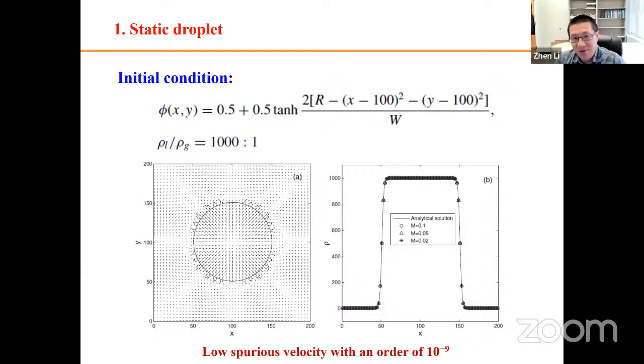Yeah, but if you do not use a non-uniform mesh, then the computational cost will be extremely high because the interface is very sharp, right? Yes, it is very sharp at the interface. This case is a benchmark problem, a static drop. For very complex problems, maybe non-uniform meshes can be used, and we can improve the results.